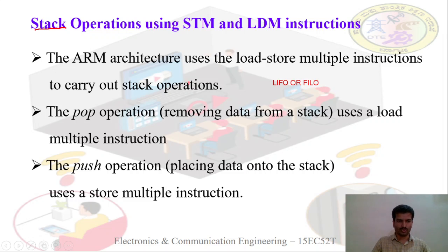It is used to store address and data while a subprogram or ISR, interrupt service routine, is executing. The stack pointer is used to access the stack memory. So here we require one pointer register, that is the stack pointer SP. The memory location where a byte was most recently stored is called the top of the stack. So normally the SP register points to the top of the stack.